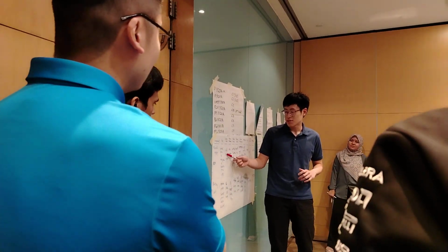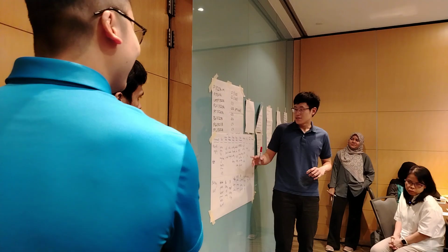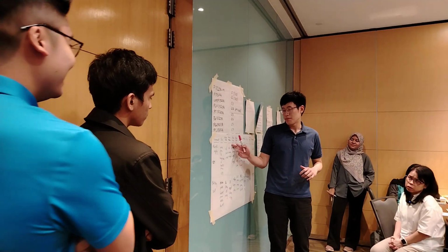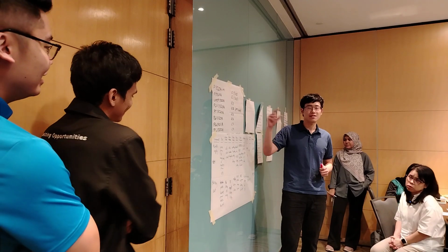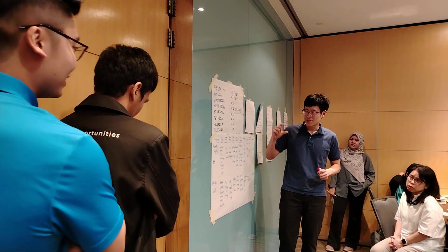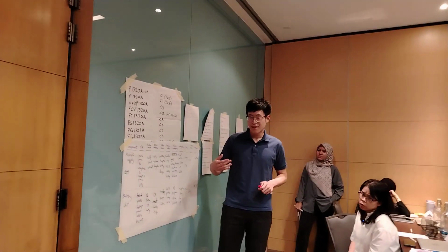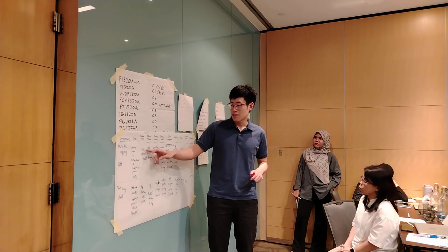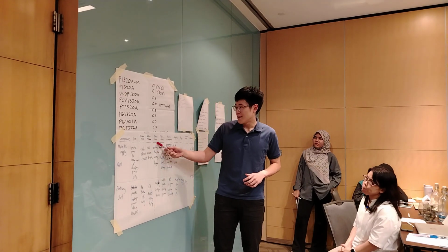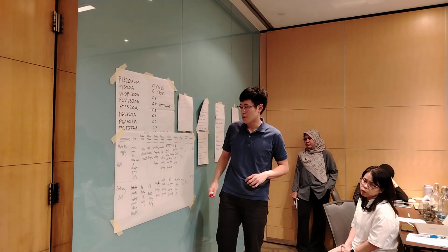The failure mode of the AC supply would be a cable short circuit, which is the underground cable that we cannot see at all. The failure mechanism is probably cable insulation degradation. The insulation normally has a very high resistance, but during the failure it will drop to maybe lower than 5 mega ohm, so the electricity can go through the grounding, causing the cable to short circuit. What can cause the insulation to go down to below 5 mega ohm?